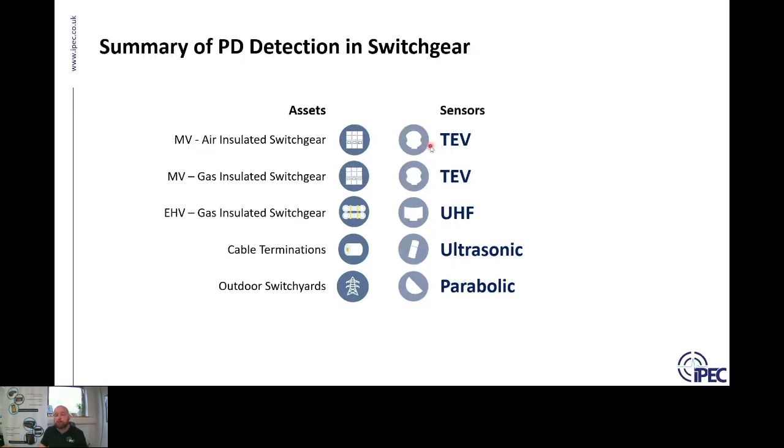There are multiple partial discharge devices out on the market. They all have different advantages and disadvantages, and they all handle that data processing in a different way. It's important to connect these sensors to a device that is effective at differentiating PD from background noise, so you can actually detect the PD signals. It's not good enough just using these sensors.